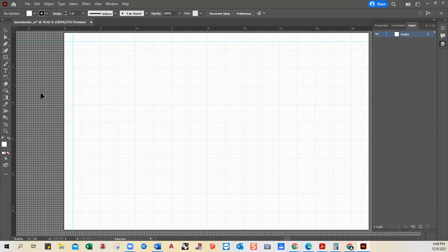And I'm going to go ahead and do that all the way around just to make sure I don't accidentally go beyond that in case we were to print this. Depending on the printer, maybe you can go up to 1/4 of an inch to the edge, but I'm just going to do 1/2 an inch all the way around. Okay, so again, I left clicked on the ruler, left click, hold and drag to pull down your guides. Once you have your guides, you can go ahead and lock them in your layers panel to the right hand side of the little eye, which turns on the visibility of your layer. If you click there in that void, that is going to lock your layer. So the eyeball is for visibility, the little lock is for editing within that layer.